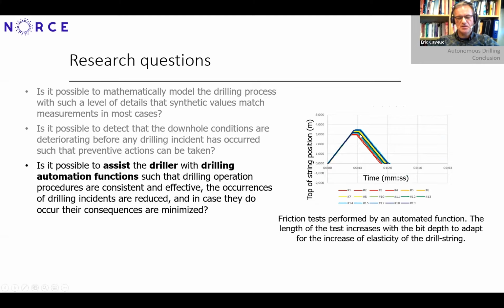But you can also notice that those friction tests are getting longer and longer as we get deeper and deeper into the well, to account for the fact that the drill string is more and more elastic, and that we need more time to get the bit movement at the bottom when we are doing the lift up and stack of sequences.